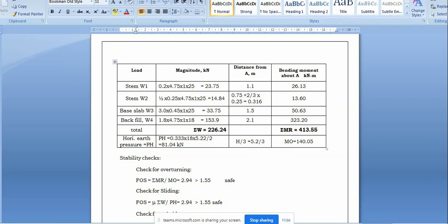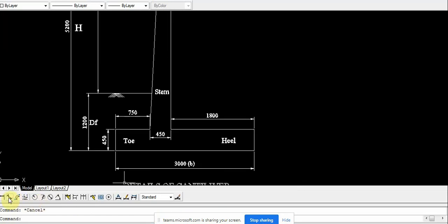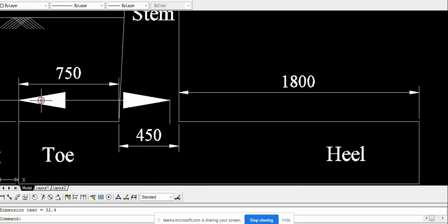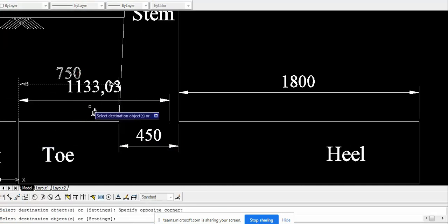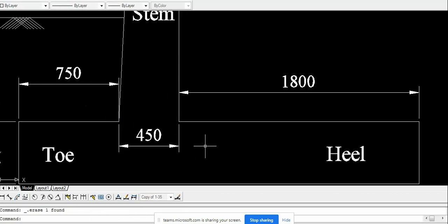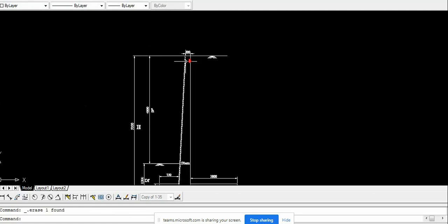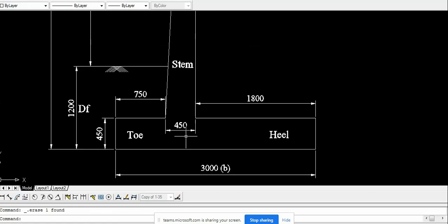You can see we want to know the CG from this end to this end. So when we take the rectangular section, 450, 200, it is 450, so left with the 250 here.